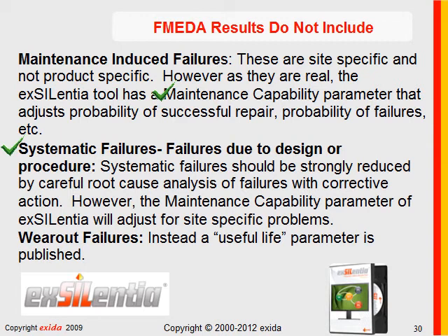I'll double check my questions one more time. Nothing. All right. Wear-out failures are not part of FMEDA data. The FMEDA data produces a constant failure rate, which has value during the useful life. In general, that failure rate should be somewhat conservative. In other words, higher than real reality.